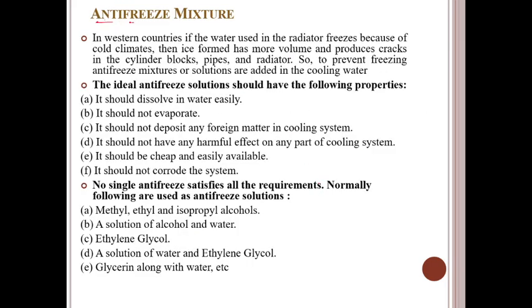Along with this, an antifreeze mixture is also used inside the water. In western countries, if the water used in the radiator freezes, because of cold climates, the ice formed has more volume and produces cracks in the cylinder blocks, pipes and radiators. So to prevent freezing, antifreeze mixtures or solutions are added to the cooling water.